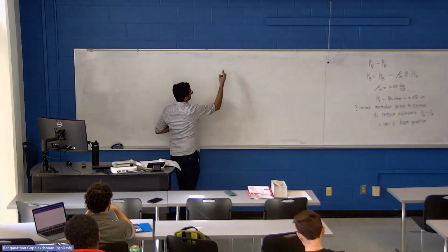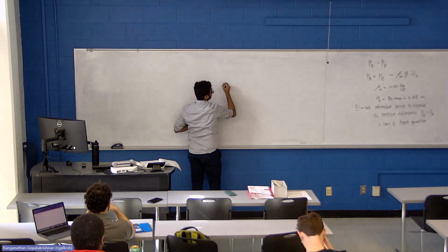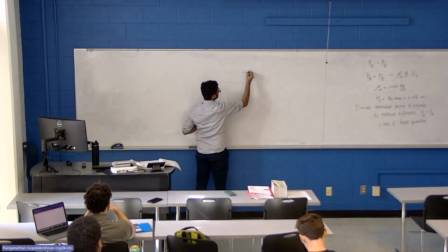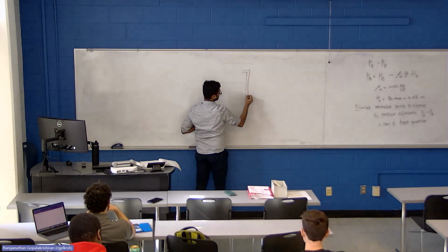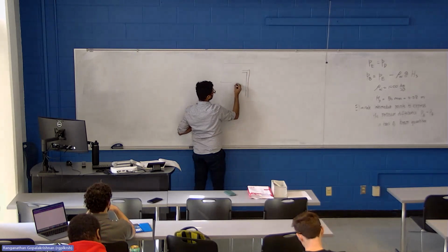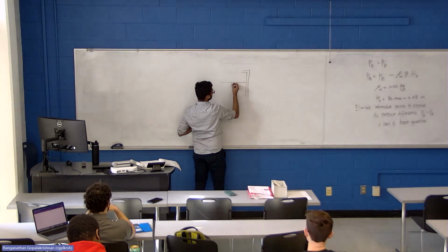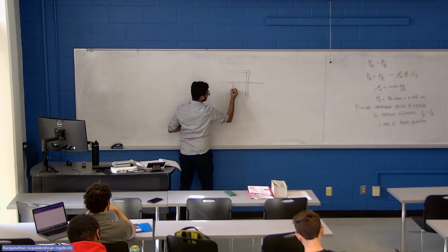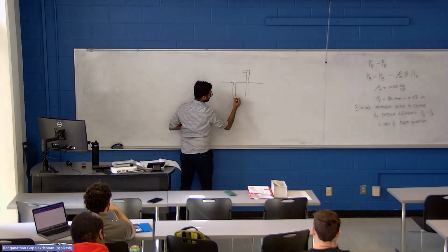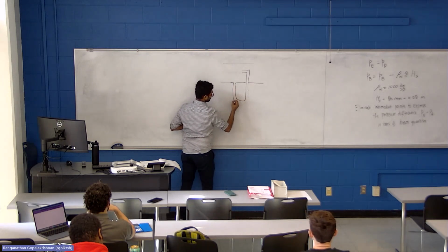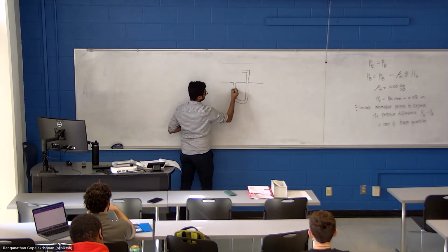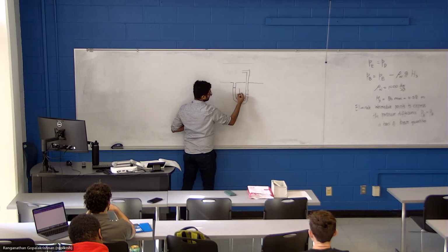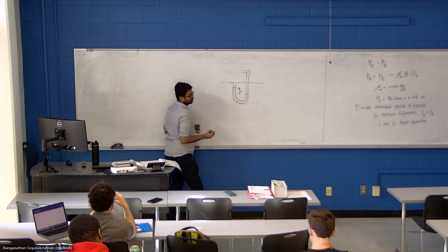Okay. So here is our pipe where you have mounted the first probe that collects all of the fluid and then brings it to the manometer. And then you have the second hole where it is drilled perpendicular to the pipe, and that is connected to the other limb of the manometer. So if the fluid here has to be above this level, this would be the height difference, right?